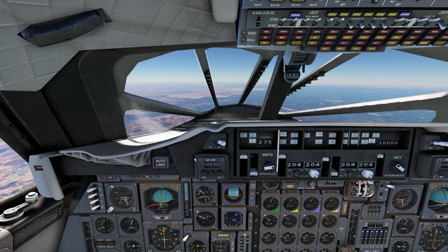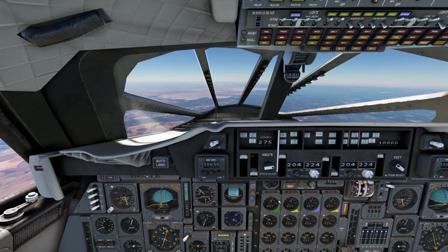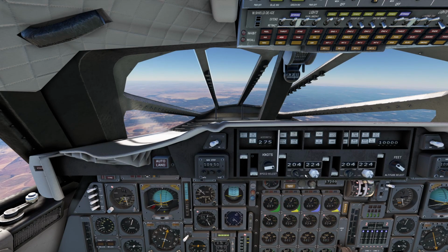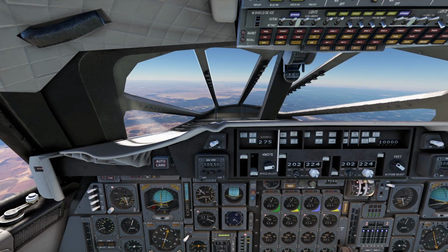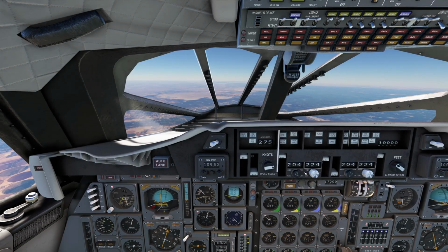About 16,000 feet, still 275 knots. I'm gonna change to RAD now, so I can take control of what's indicated in the VOR, because we have pre-programmed the ILS. I put the same track in as is in the INS at the moment. You can change to RAD and go to track. Plane should actually continue to fly, but now you are controlling it via the track setting.